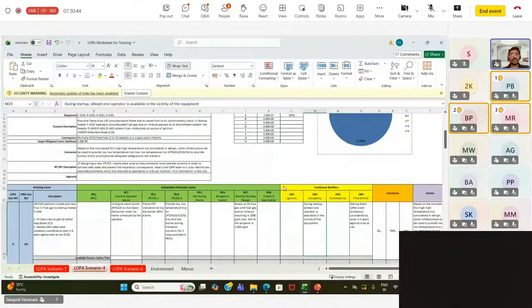So you need a certain stoichiometric ratio for fuel to air or air to fuel to sustain the flame. Since here the fuel gas flow is constricted or there is partial flow of fuel gas, it is not able to maintain this fuel to air stoichiometry in the startup heater, and that could lead to uncombustible fuel gas and air mixture passed on to the downstream, because the flame is not able to sustain due to the inefficient stoichiometric ratio.